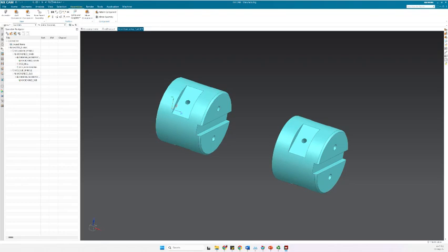Next, what we need to do is to move the subspindle machine coordinate system to the subspindle part. And for that, we need to again go back to our home so that we go again to the mill turn one. And then we go now to the machine coordinate system in the subspindle. So we have the subspindle here. And then I have the machine coordinate system in the subspindle. I should have it here.